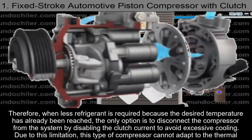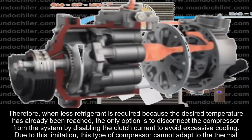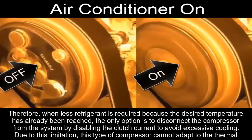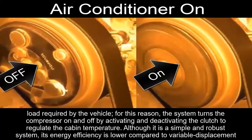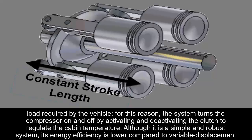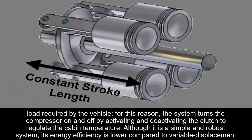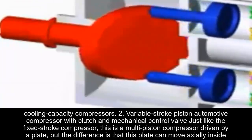Therefore, when less refrigerant is required, because the desired temperature has already been reached, the only option is to disconnect the compressor from the system by disabling the clutch current to avoid excessive cooling. Due to this limitation, this type of compressor cannot adapt to the thermal load required by the vehicle. For this reason, the system turns the compressor on and off by activating and deactivating the clutch to regulate the cabin temperature. Although it is a simple and robust system, its energy efficiency is lower compared to variable displacement cooling capacity compressors.